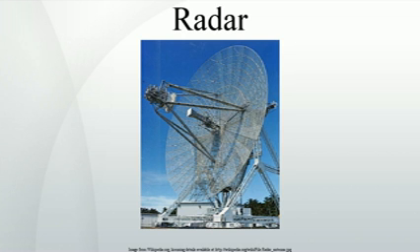Phased array. Another method of steering is used in a phased array radar. Phased array antennas are composed of evenly spaced similar antenna elements, such as aerials or rows of slotted waveguide. Each antenna element or group of antenna elements incorporates a discrete phase shift that produces a phase gradient across the array. For example, array elements producing a 5-degree phase shift for each wavelength across the array face will produce a beam pointed 5 degrees away from the center line perpendicular to the array face.